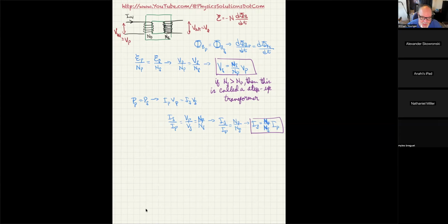Now that we have that, and your book has a lot of examples to show you how much energy that saves, the main thing is realizing that P is equal to I squared R. You might also recall that P is equal to V squared over R, and I told you that we step up the voltage so that the current goes down, and I pointed at I squared times R as the voltage, or excuse me, as the power loss. Well, you might say, what about V squared over R? Since we're stepping the voltage up, that means the power loss is going to be even worse.